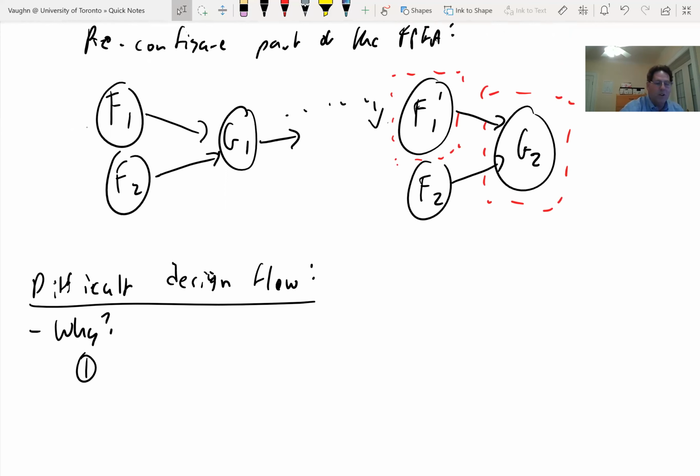These might be difficult questions, but yeah, so there's compile time for the new function. That's probably okay, but it would be a problem if you had no idea what the new function is. But if you as a hardware designer knew I've got the following 2 or 5 or whatever functions, you could pre-compile them all. Partial reconfiguration is not going to recompile them. It's just going to load in those bits of bitstream.